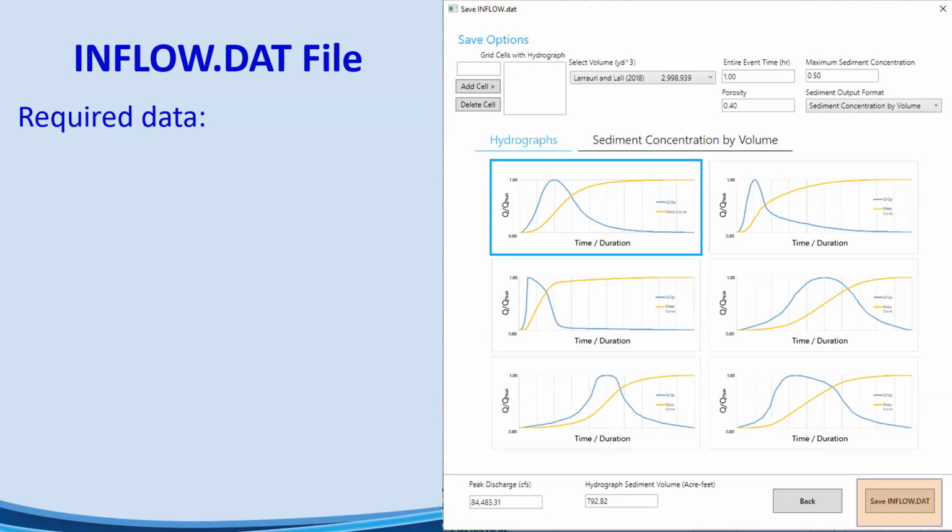So if you want to generate a worst case flow hazard scenario, for example, you may want to select the front loaded hydrograph, okay, where the volume is going to release pretty quickly in your system and is going to move downstream pretty quickly in your domain. One of the beauties of this tailing dam tool is that you can select different hydrographs, and you can run pretty quickly the FLO-2D model with this mud flow condition, and see what is the hydrograph that is giving you the worst case scenario, the worst case flood, okay?